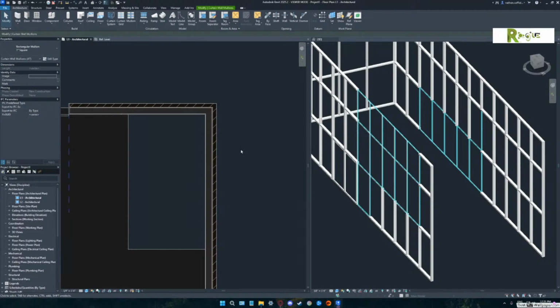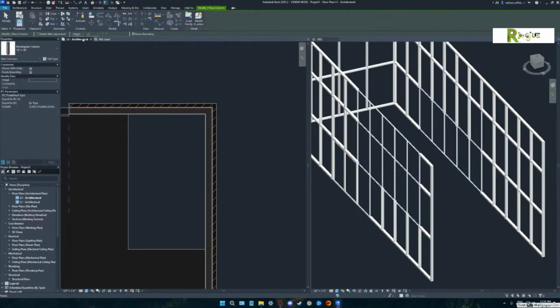What I was trying to get across to you, what people don't understand about what an architectural column does, is if it hits a wall, it has a magic ability to take that finish and wrap it around the column. So if you were to hit column right now and put the architectural column in, remember it's going to remember that rectangular. Now, don't go near the corner. Don't go near the corner.